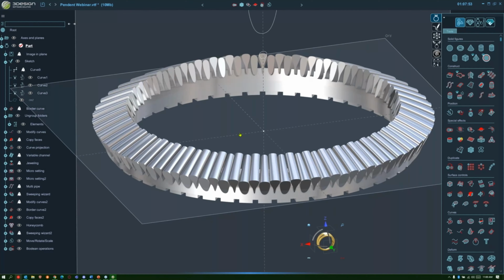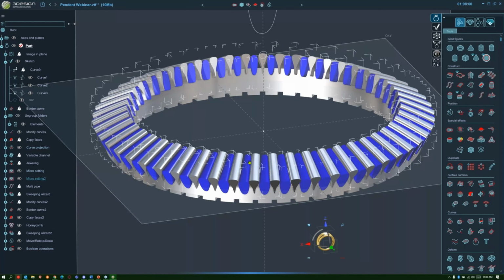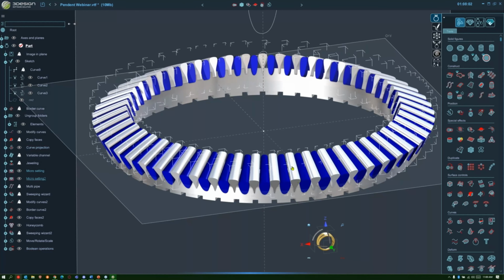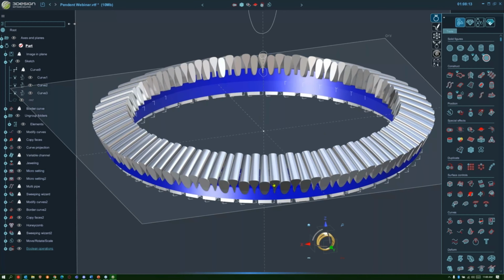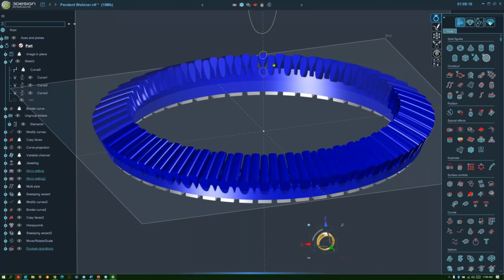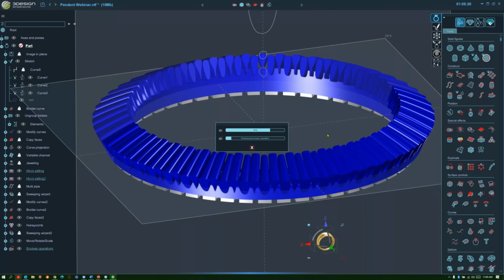Another strategy, which Robert has also mentioned, if you're having problems with these group cuttings like this, so this is actually just a group of many different cutters. Sometimes you can Boolean those to themselves so it's one part, and then Boolean it if you're having trouble. Again, I always save and then try it without worrying about that first. So we're going to do a Boolean subtract, and it's kind of cutting through pretty easily so far.